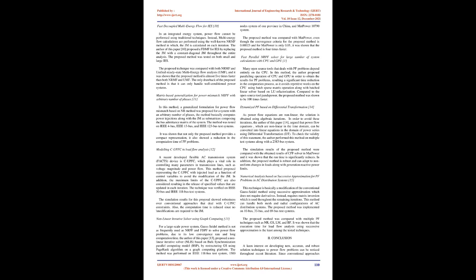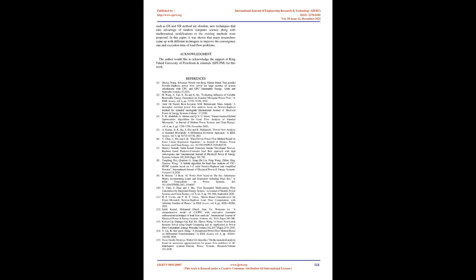The technique was verified on IEEE 30 bus and IEEE 118 bus test systems. The simulation results for this proposal showed robustness over conventional approaches that deal with UPFC constraints. Also, the computation time is reduced since no modifications are required to the Jacobian matrix.